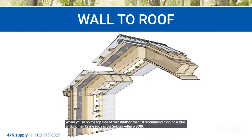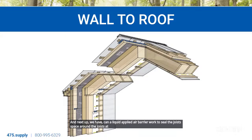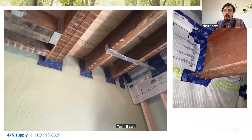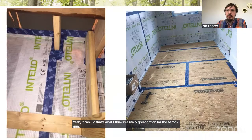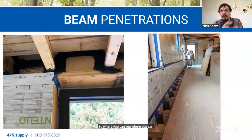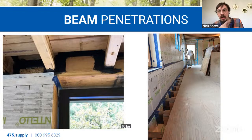And next up, we have, can a liquid applied air barrier work to seal the joist space around the joists at the rim board, etc.? Yeah, it can. That's what I think is a really great option for the Aerofix gun. You can see in this image on the left, that's what the black is. They sprayed with the Aerofix or the Viscon to be hitting those joints. So that's a great approach.